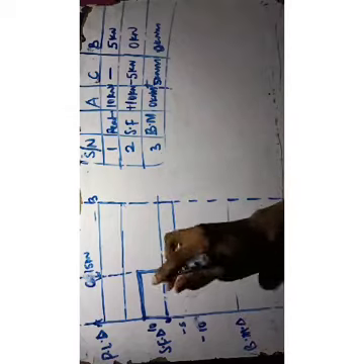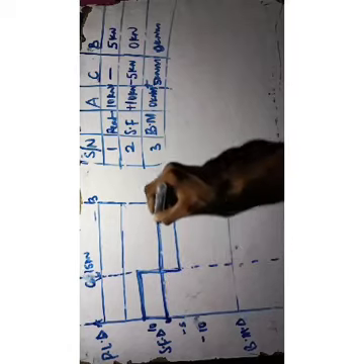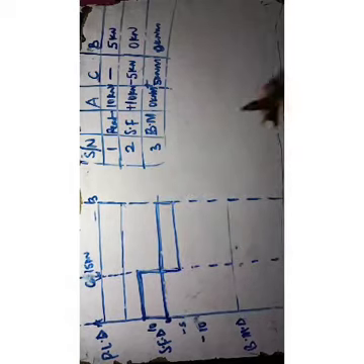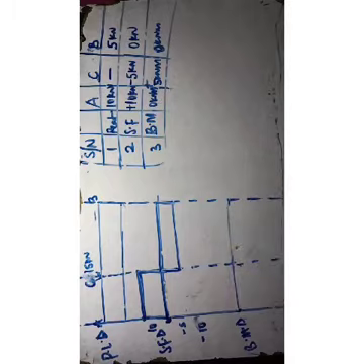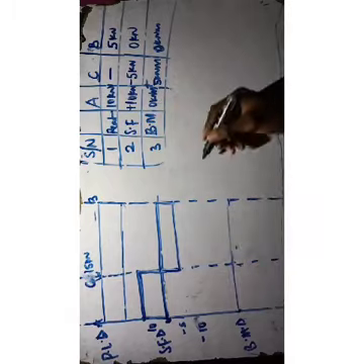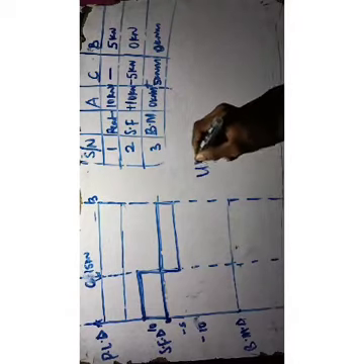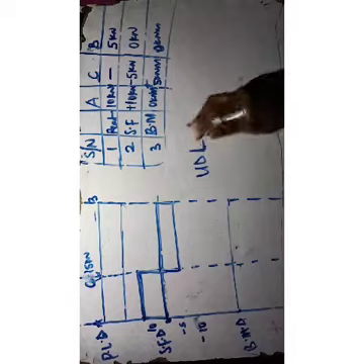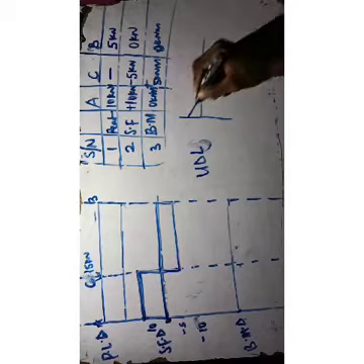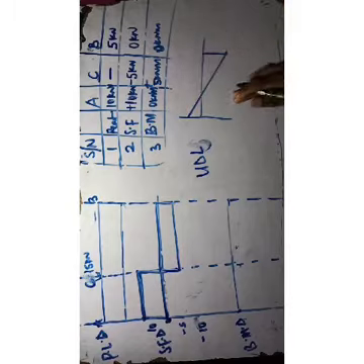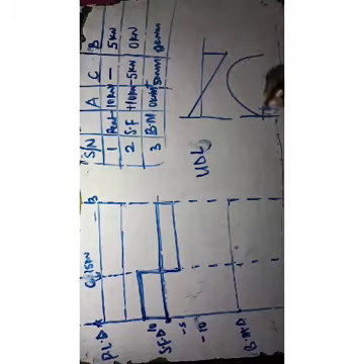So the bending moment diagram will now be as well. You have this. So the bending moment diagram will be at point A, you have 0, 0. I told you that the bending moment diagram for ordinary simply supported is always straight. If it were to be UDL, that is uniformly distributed load, you have your shear force to be something like this, and you have the bending moment to be something curved like this. That is for UDL.